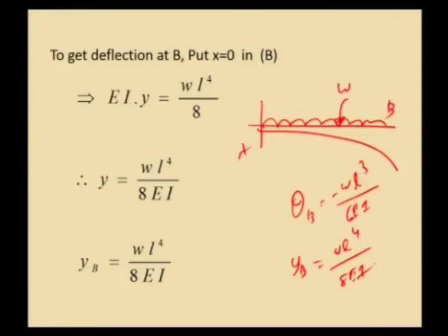So, these are the standard loading cases for which we have obtained the slope and deflection by the use of the double integration method. The method of double integration, from the name itself, says that we need to do the integration two times, therein involving 2 constants of integration which are solved using the boundary conditions of the problem. In case of a cantilever beam, we will have slope and deflection at the fixed end as 0. Using that boundary condition, the constants of integration can be found and substituted to get the general equations for slope and deflection, which give us the values for these 2 standard cases.